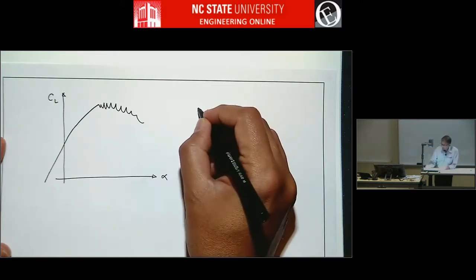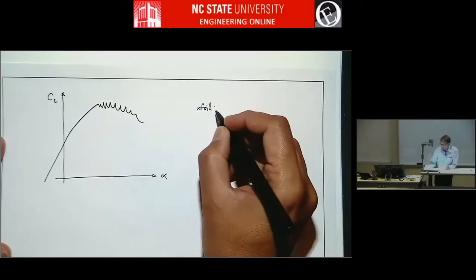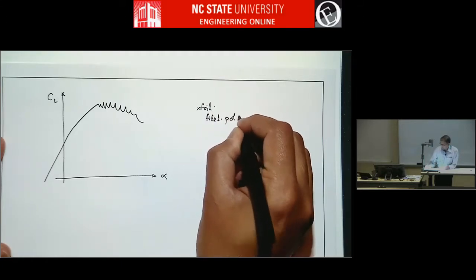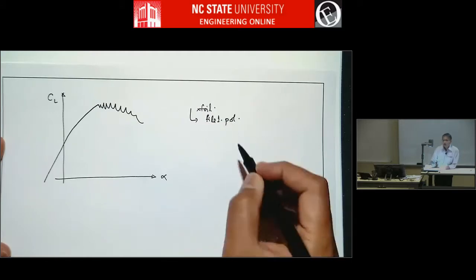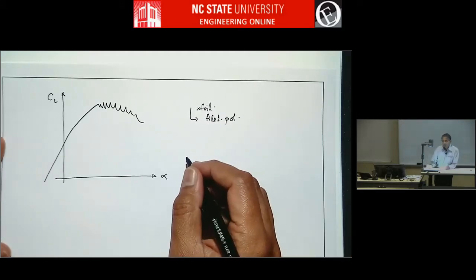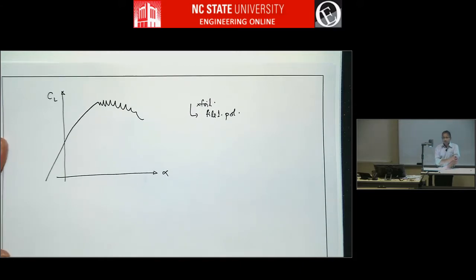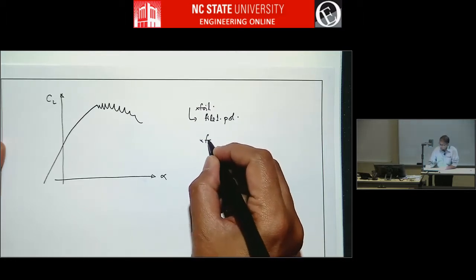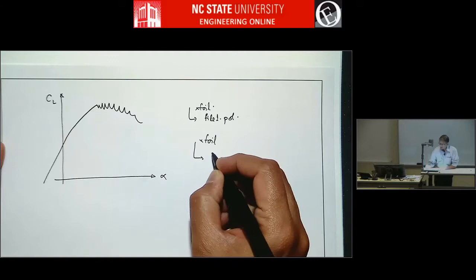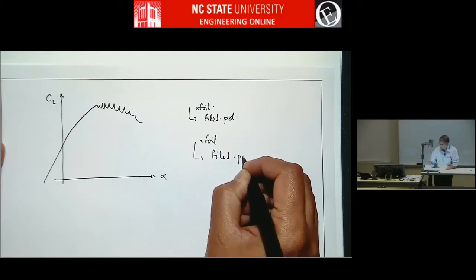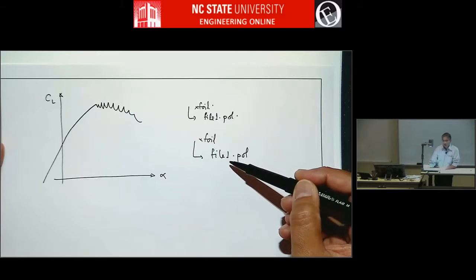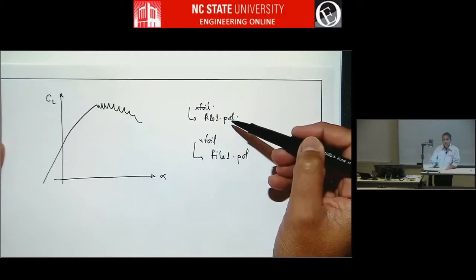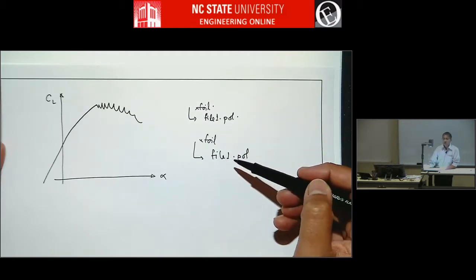When you run Xfoil, and let's say especially if you're using a script file and you're creating some, let's say, file1.pol polar, right? So it'll write this out. Next time let's say you make some small modifications and you run Xfoil and create the same polar file. So Xfoil does not, it looks like it does not overwrite the earlier file. Suppose you say file1.pol again, and this file is still there in your folder. Xfoil will not overwrite it. It will actually append to the file.